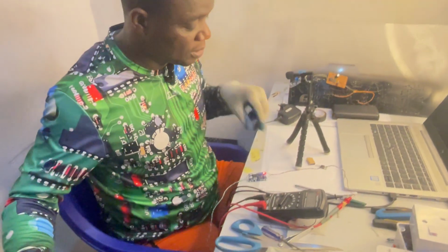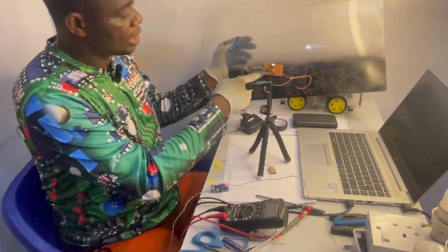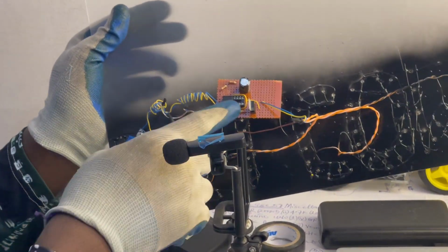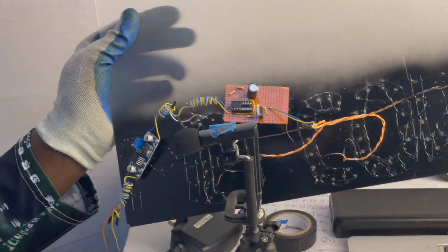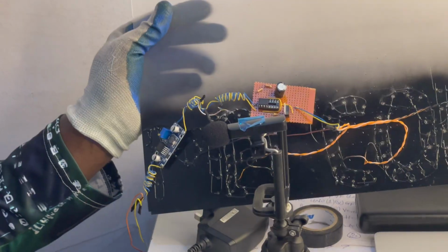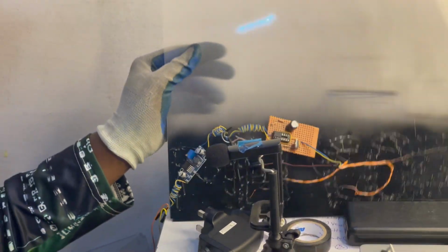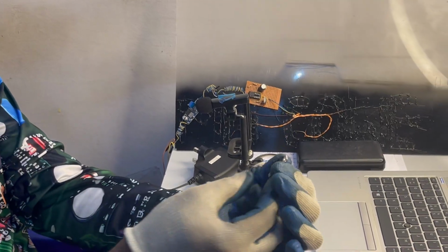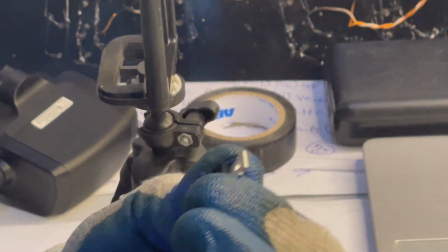Now quickly, the transistor you see here, as I said, is a BJT, exactly TIP41. That's the one I use, TIP41C. When it's facing you this side, the way to count it is from left to right: BCE, base, collector, and emitter.